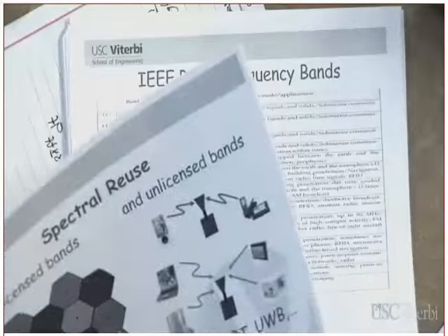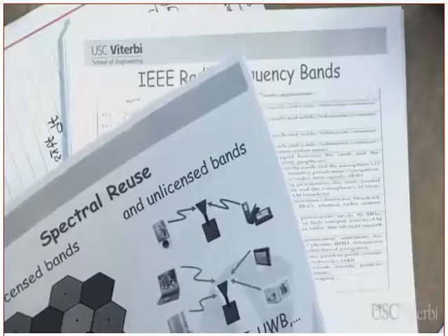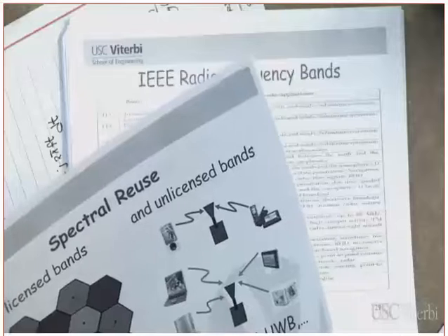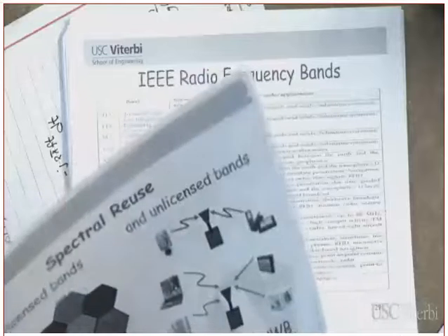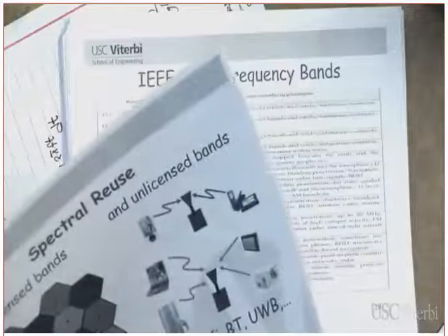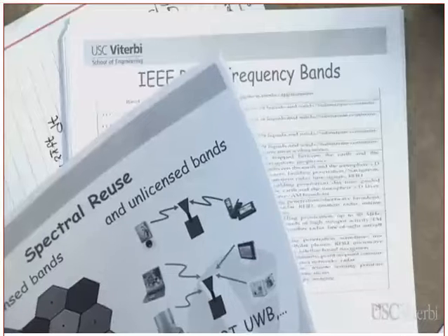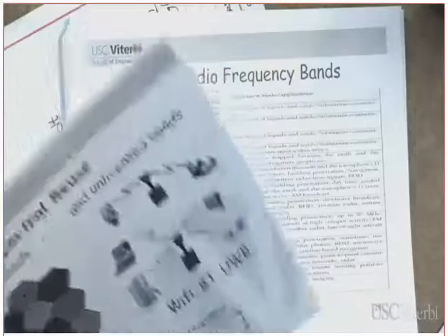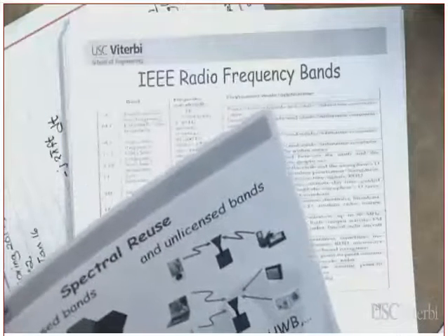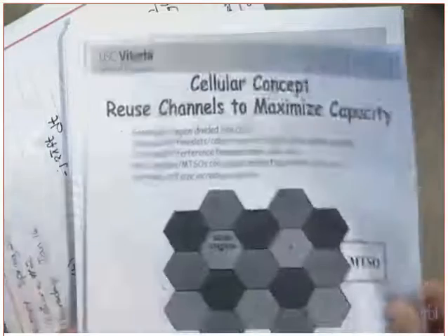Always remember the rule of thumb. When you design an RF system, at the beginning you design it for coverage, which means you want to cover as much as possible. After you design it for coverage, then you try to improve it to increase capacity. The coverage becomes more important at the beginning than the capacity.